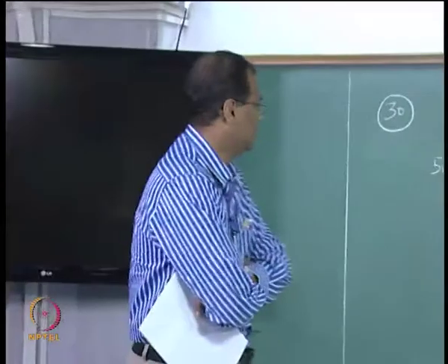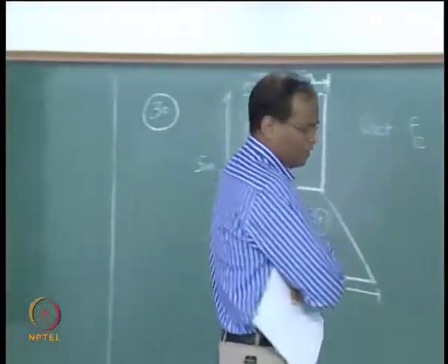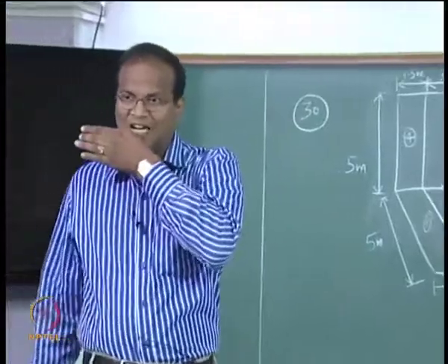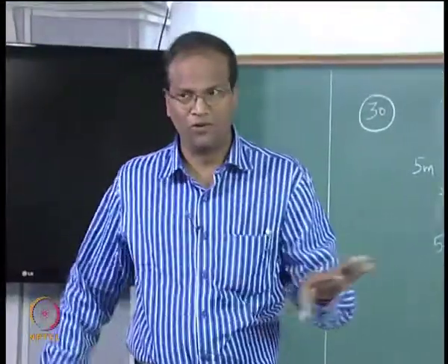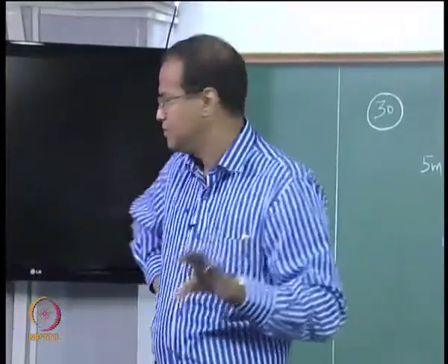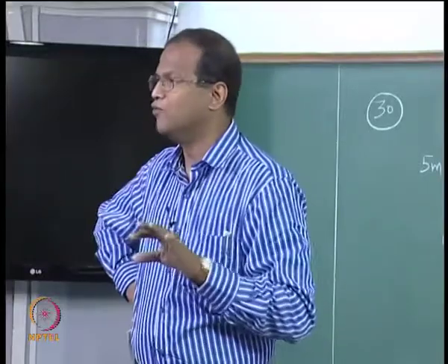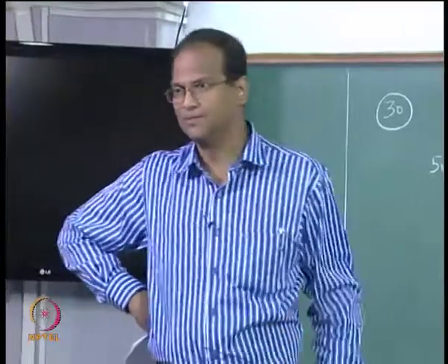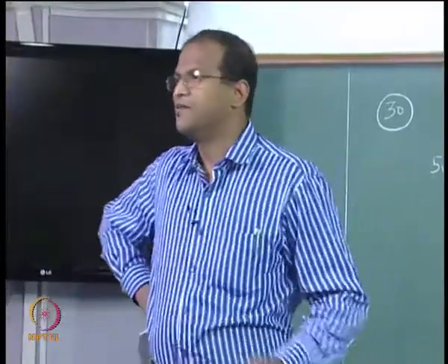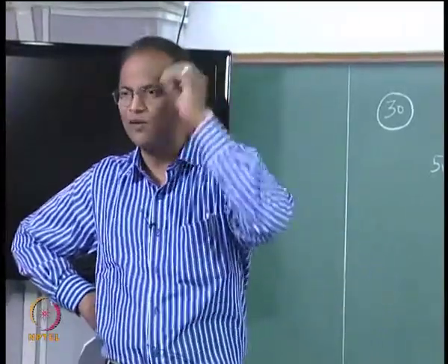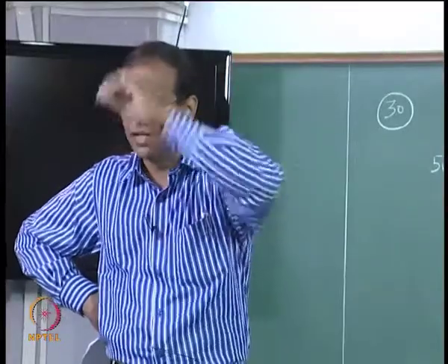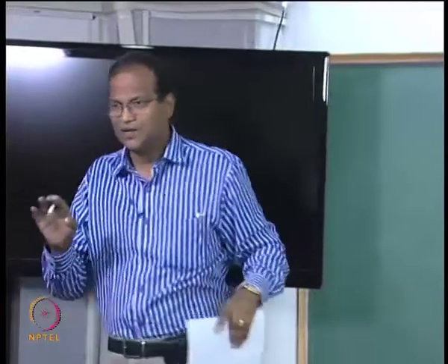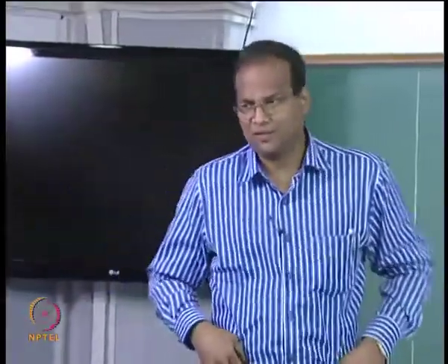Please start slowly. A good strategy would be to first write A1, A2, A3, A4 and then A24 and A13. Write the 6 areas first. Then calculate all the view factors which can be determined from the chart. And then start your algebraic manipulation.